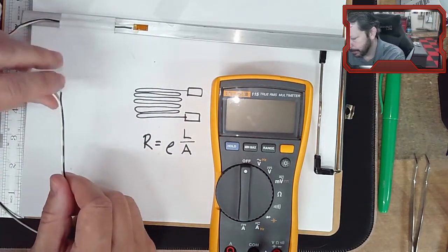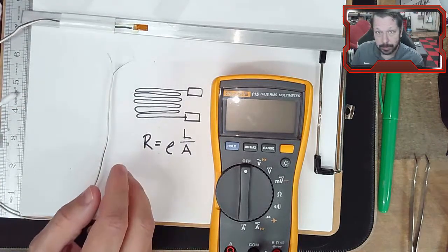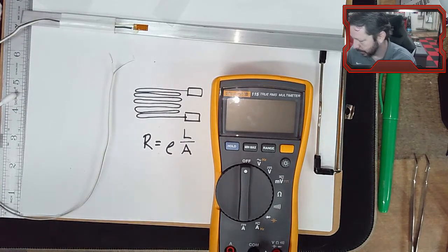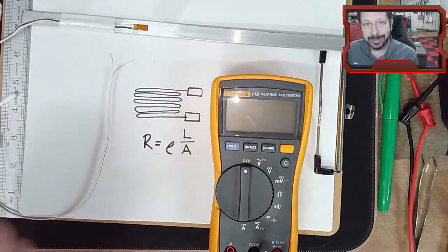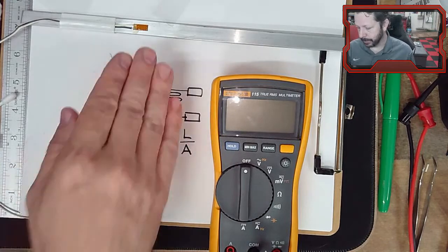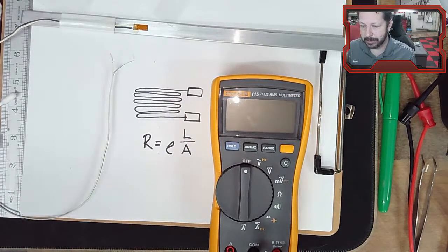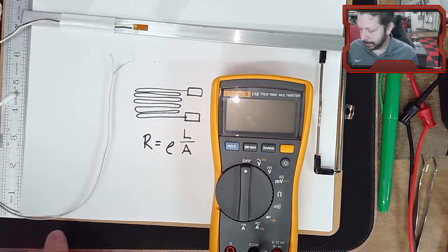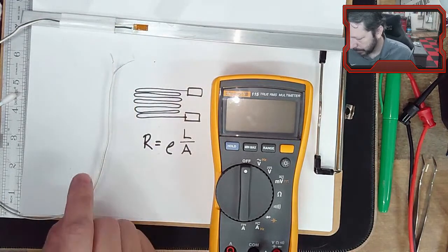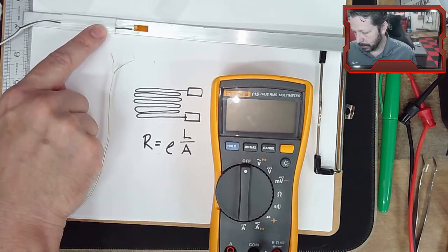We're going to wire it up in a 2-wire arrangement, but there are 3-wire arrangements and other types of arrangements. Sometimes you actually have to send a voltage to excite the strain gauge. We don't need to do that for this. We're using it really as just a resistor. And it's good. So it says that it already has lead solder to it. So you don't have to do the soldering part then. You just have to do the mounting part. Still relieve this, the wire.